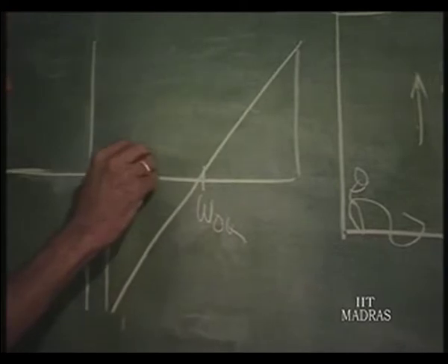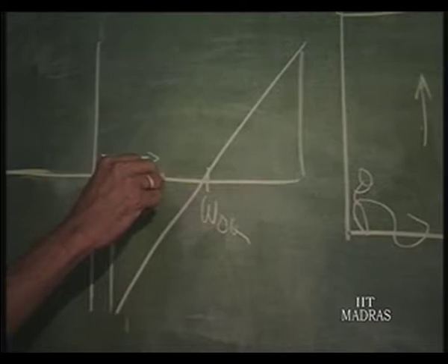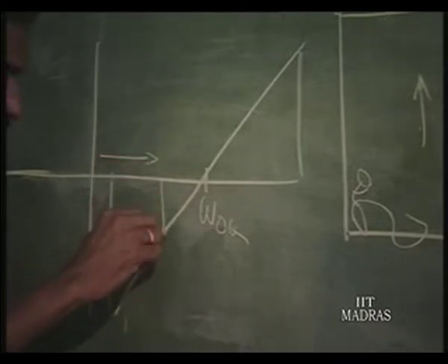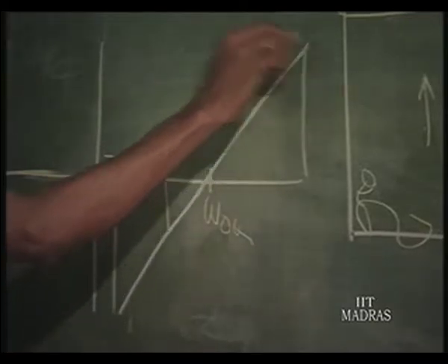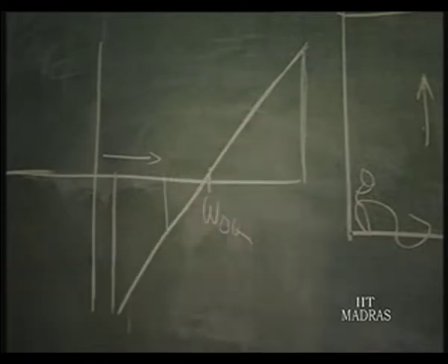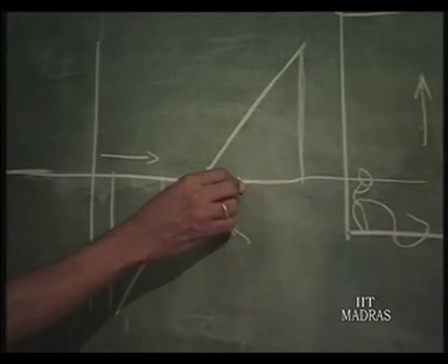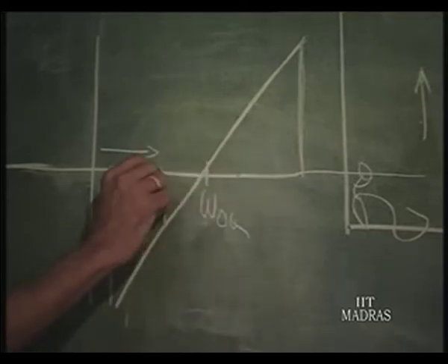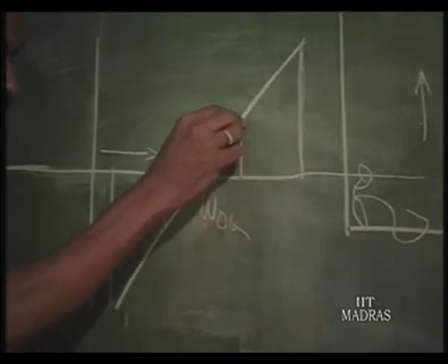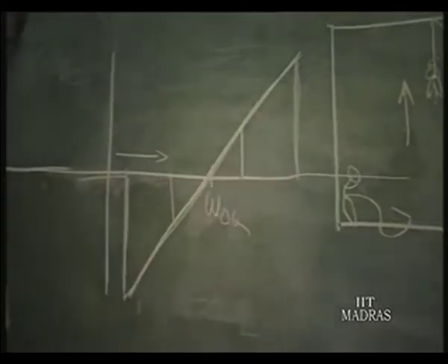in fact, when I am coming from here, let us say at that frequency this capture has just occurred, then immediately it will lock to the incoming frequency and it can go on like this. It will go out of lock here. Then when I come from this side, I have to come pretty close to omega naught q, as much close to omega naught q as on the other side. So, it will get locked to this and it can go on remaining locked. So, this is the way, if you come from these two sides, the response is going to be.